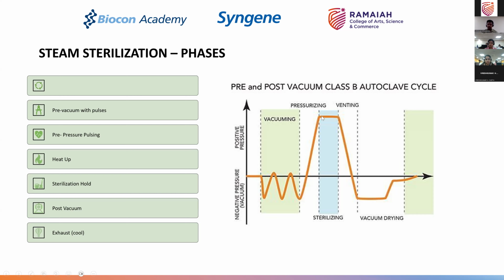During this period, the temperature and pressure do not go below the set value of 121 degrees centigrade. It may still fluctuate within the tolerance that I spoke about, but the automation and controls are built in so that it never falls below the lowest validated temperature of 121 degrees centigrade and does not go too high. During that time, some amount of steam may get introduced if the temperature is seen falling, and the temperature will fall because of one simple reason: there is some amount of condensation continuously happening.